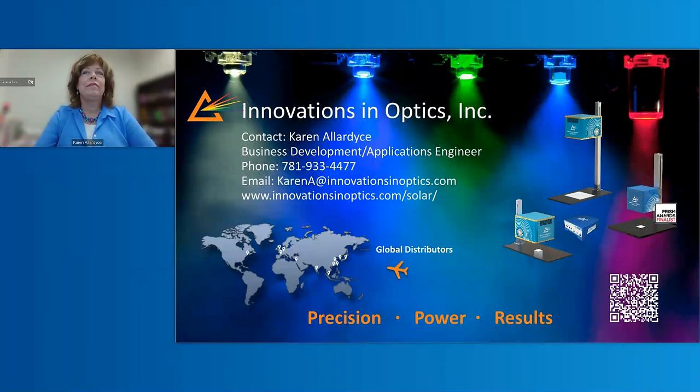Regarding the LumiProbe module, how do you handle stray light? Okay, a standard practice is to take a dark scan that allows you to subtract out any noise from the signal. Another option is to have a dark box. We're presently considering designing that now. But those are standard approaches to controlling the stray light. One thing is that if you're using any of the LumiSuns, they have a very high brightness and high level, so the noise isn't as important.